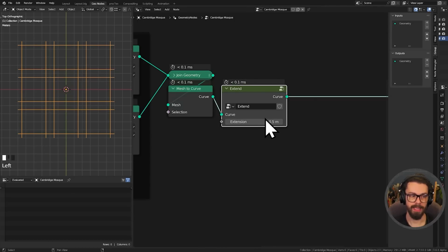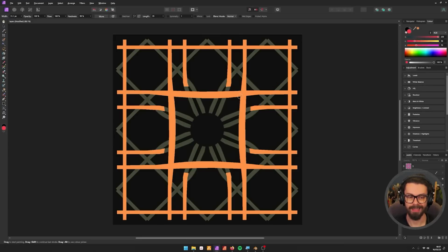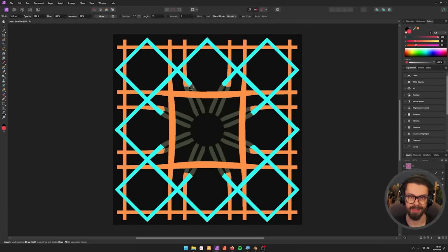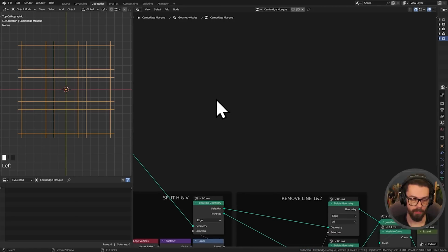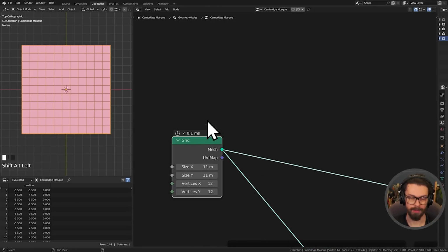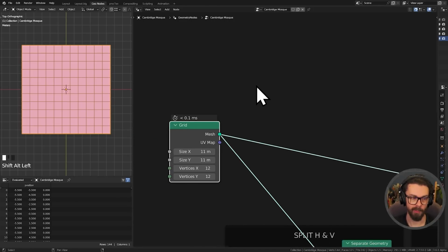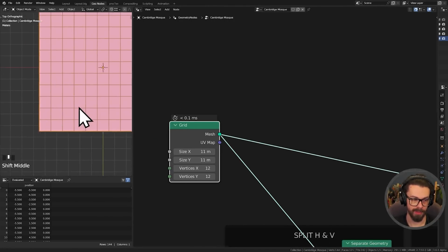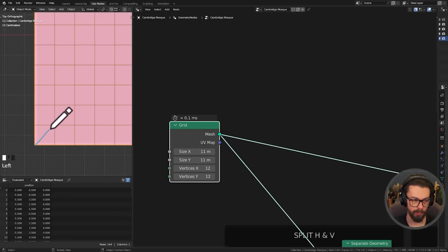So this is our main grid. And clearly there's a little bit more going on here, but we will kind of break into that as we move forwards. Let's for now have a look at creating our diagonal grid, which is going to sit on top. We are going to be using the exact same starter grid. This is very important. And we're going to be creating our diagonals by joining across each face, just like this. And then we're just going to use these lines, so we're going to ignore everything else.